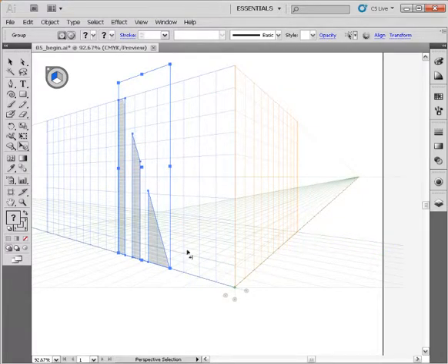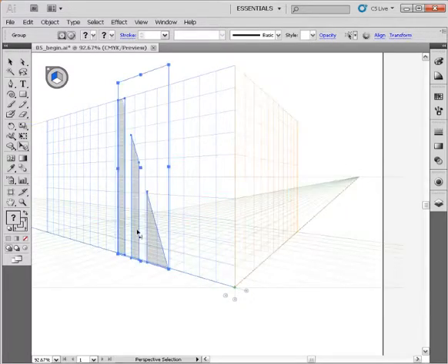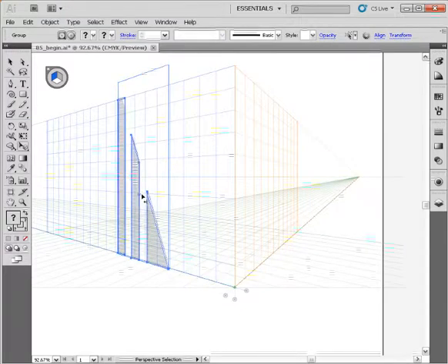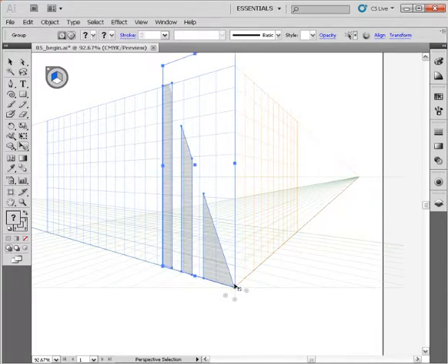And I tell you what, let's go ahead and talk about this cluster of objects, or these three objects we have selected here. Now, we can see here there's a bounding box, and let's just say we want the bottom right corner of these three objects to sit right on our origin right here, right at the 0, 0 point for our X and Y axes. So how could we do that? Well, being that that's the origin and it sits on these grid lines, we could use our Snap to Grid feature and just hold down Shift. Well, let me go ahead and select all three of these objects here. And we could just grab all three of them and slide them along and snap them to that X-axis here. And you can see that because the 0, 0 sits on grid lines, we can snap to that here.